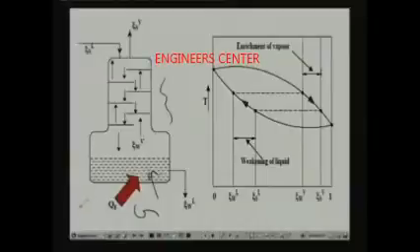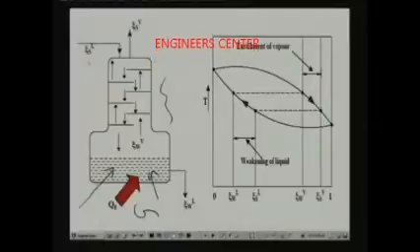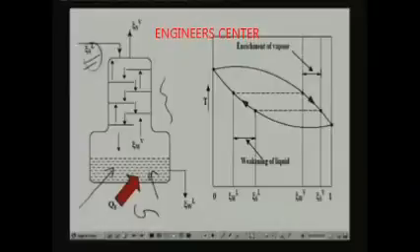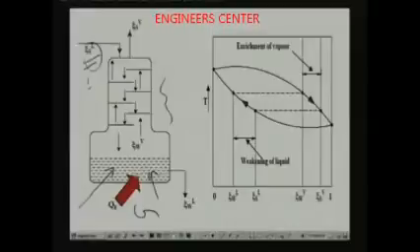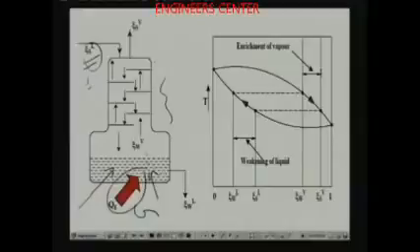In the generator you have a solution of ammonia and water, and from the top strong solution of ammonia is coming. This is what is coming from your absorber. Heat is supplied to this solution bath at the bottom portion. As a result, vapor is generated. This is the vapor moving up, and the vapor has an initial concentration of ζWV.